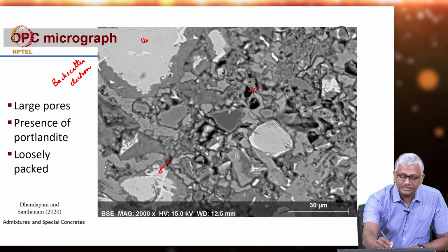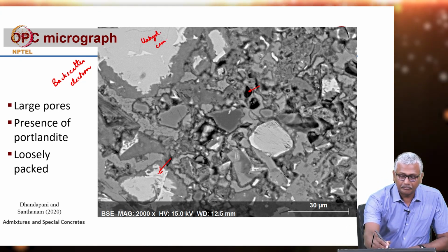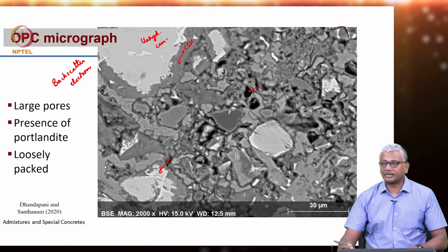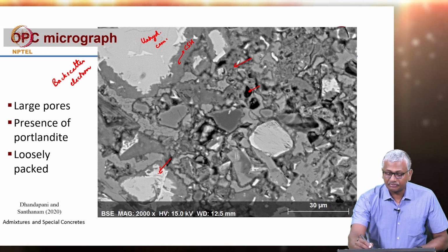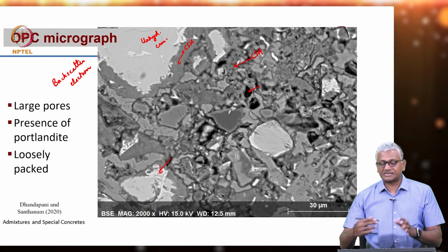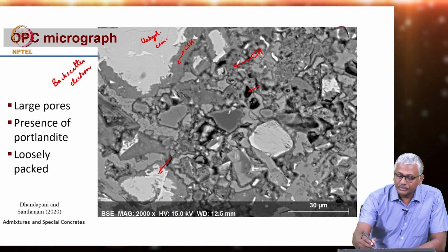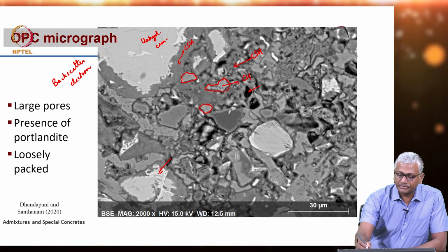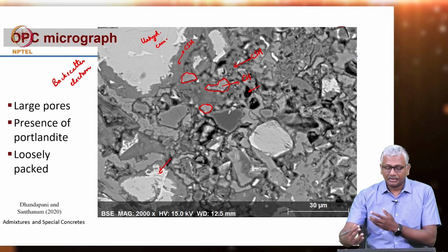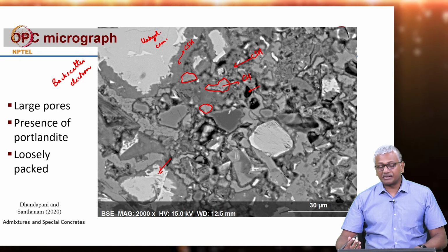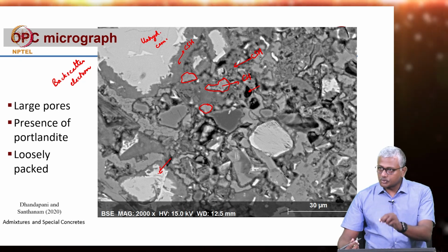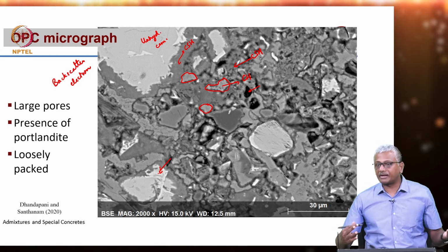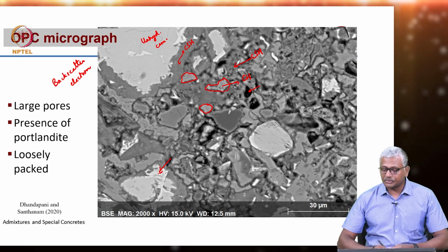You have the unhydrated cement here, right. You have a hydration ring on top. So, this is CSH right outside the unhydrated cement. This is CSH which is also present, but that is outside the surface of the unhydrated cement. You see some brighter phases, these are calcium hydroxide, those are calcium hydroxide phases. Similarly, you can also make out ettringite sometimes, because ettringite is usually present in particle sizes which are too small to be detected as individual phases, unless there is a sulphate attack, in which case there is a lot of ettringite formed, there is a lot of gypsum formed, where you will start seeing those compounds in a large way.